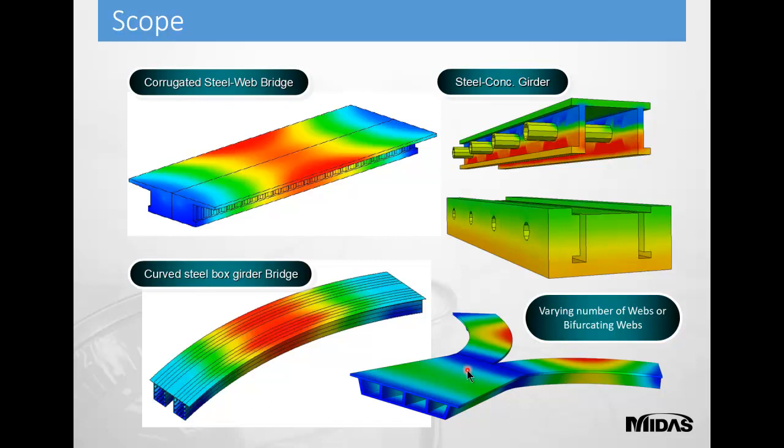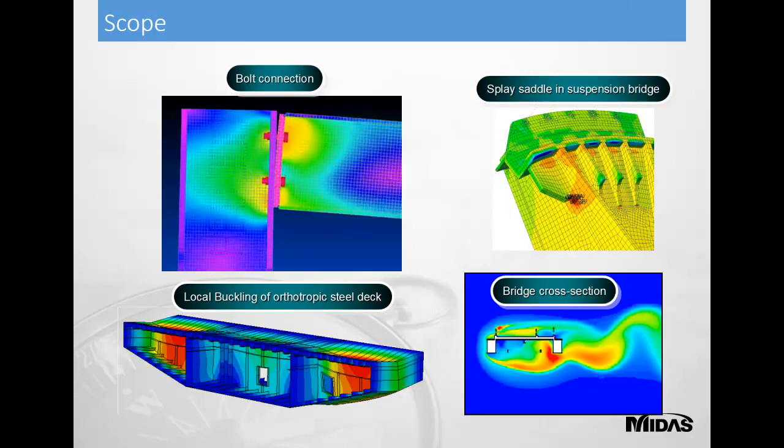Here the stress concentration will be at the location of the bifurcation. So to get the accurate stresses in this crucial location, we need to go for detailed finite element analysis, which will be done in MIDAS FEA.